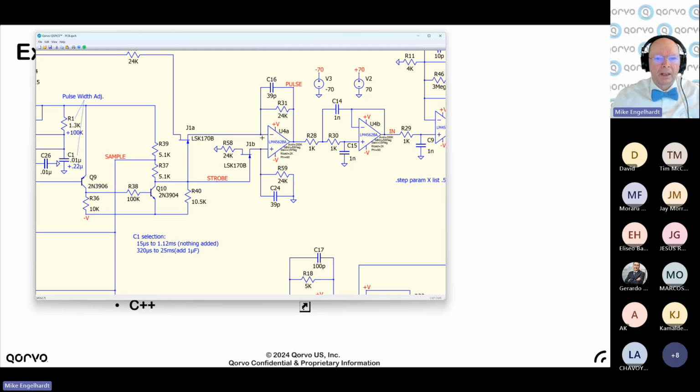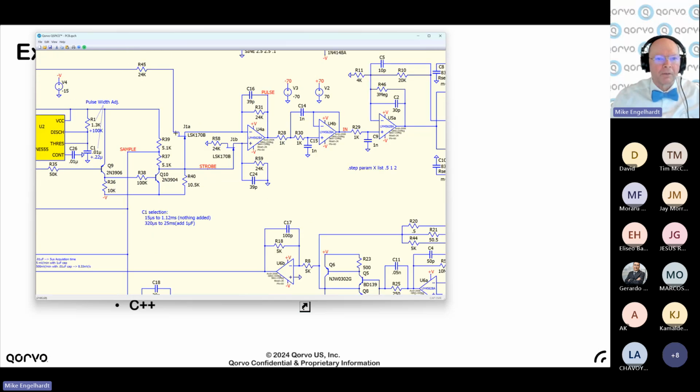You put the JFET into the virtual ground of a transimpedance amplifier, and you add a resistor in series with the JFET. So the JFET's already on, basically is not a critical part of the circuit. So in this circuit, if this JFET is on, then it's an inverter. It's a -1 inverter. If this JFET is off, it's a voltage follower, and the voltage on the output would just be the voltage on this node. So this node is usually ground. So let's ground this node and show the normal operation.